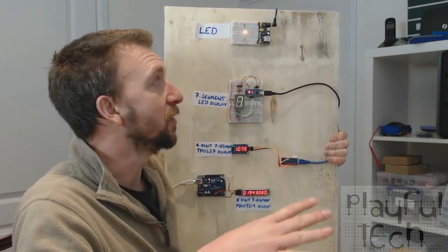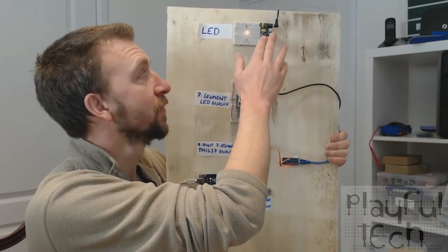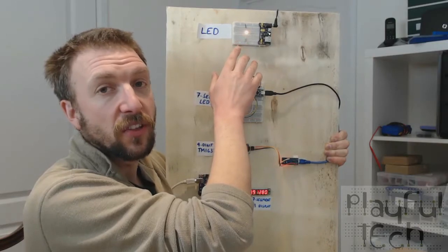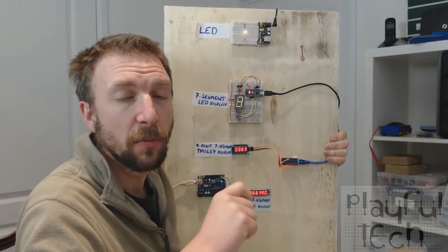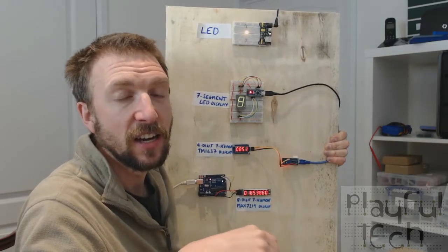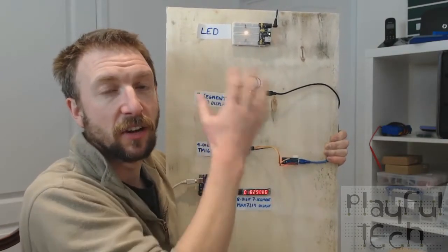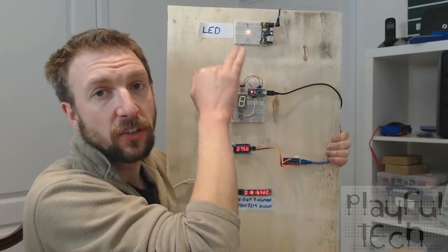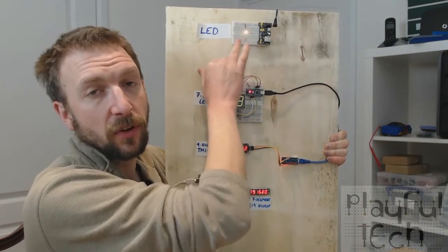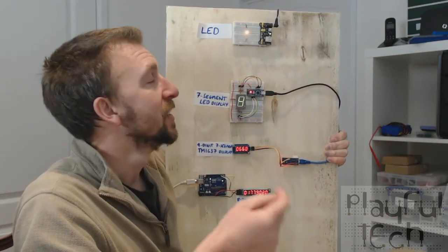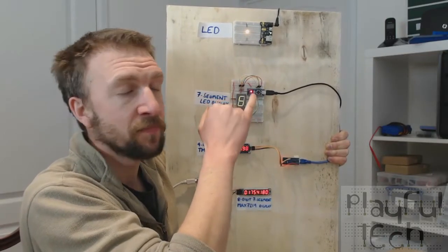To do that, you take your input voltage. I'm supplying 5 volts input here. You find out the forward voltage across the LED. Different coloured LEDs have different characteristics. It will normally be printed on the data sheet that comes with the LED, but if you can't find that, you can make an approximate guess based on the colour and look up online. This LED has a forward voltage of 2 volts. I'm supplying 5 volts, this has a forward voltage of 2 volts, and you work out the difference between them. That's 3 volts.